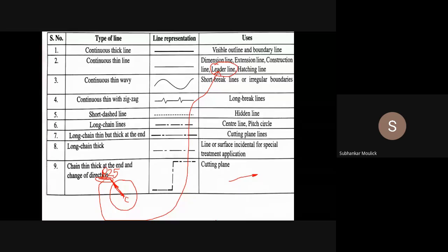This is a circle when I have represented the circle in terms of radius. If I want to represent the circle in terms of diameter, what will I do? Again, this is a circle. Locate the center point of the circle, C. If the radius of the circle is 25 mm, what will be its diameter? 50 mm. Diameter is 50 mm. How will I represent it? By the help of a leader line.